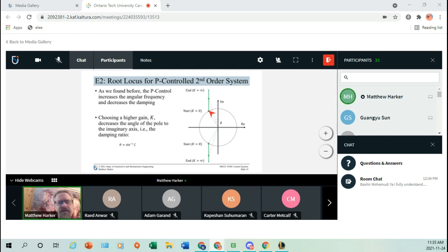So that's just saying, like, if you have a mass spring damper system, a simple second order system, and it has a damping ratio of 0.5, you could then, and a fixed, I basically chose this as the omega n is also just chosen arbitrarily as a kind of normalized factor to be on this circle, right? So if we increase the natural frequency of the system by changing the spring or whatever, that circle would be bigger or smaller, right?